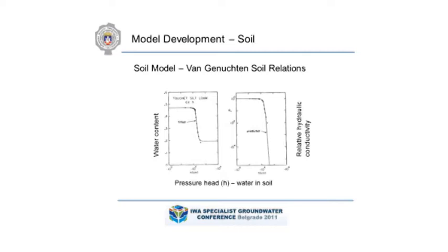So an attempt was made to create a model under a probabilistic framework. This 1D vertical numerical model was used to analyze the long-term infiltration process and to evaluate the effects of aquitard heterogeneity on the annual recharge intensity of the aquifer. The model uses meteorological data, including daily precipitation data, to estimate the potential evapotranspiration using the standard Penman-Monteith model.